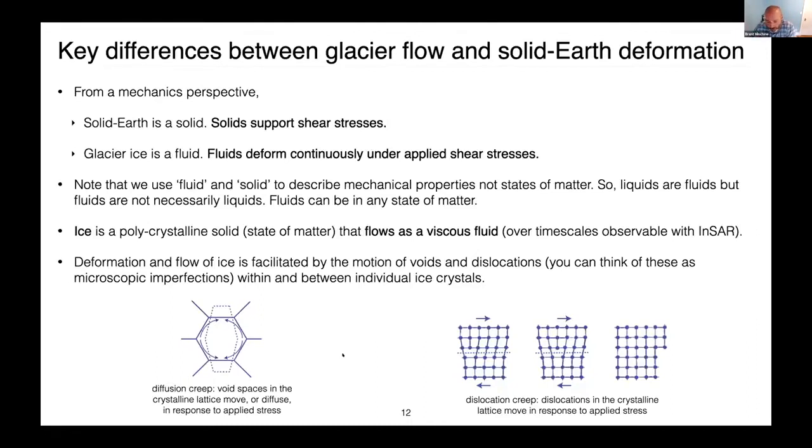to deform fairly readily. In addition to that, ice is a polycrystalline material, with lots of water molecules, just H's and O's, all connected together. Individual water molecules are connected into the crystalline structure of the ice through hydrogen bonding and so forth. Those connections are imperfect. You put all of these things together and there will be what we call dislocations, places where there maybe should be a bond, but that bond is not able to be connected. So as the material is sheared, that dislocation, that connection moves through the material and the actual structure kind of moves in a stepwise fashion.